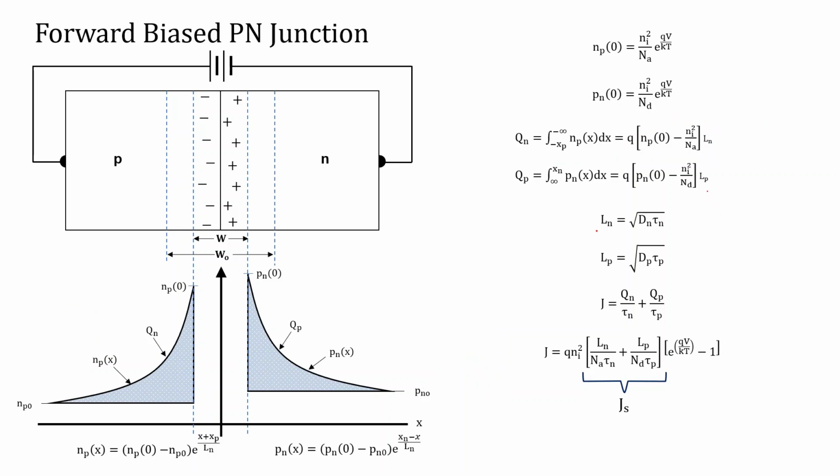Now this is an important concept, diffusion length of the electrons. So this is the average diffusion length, that when an electron moves from one region to the p side, and then it recombines with the holes and then they diffuse. So the average length, you can say, by which an electron travels in the p side. So this is diffusion length given by diffusion constant Dn multiplied by excess carrier lifetime of electrons. So this we have already discussed earlier.